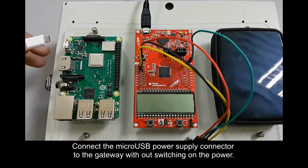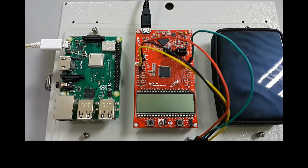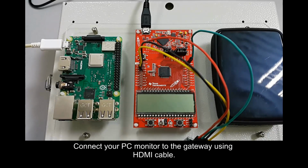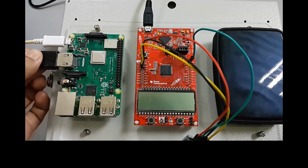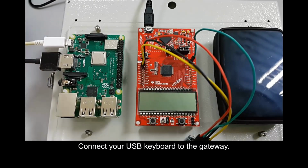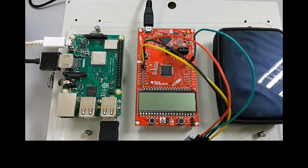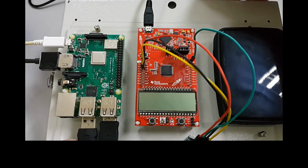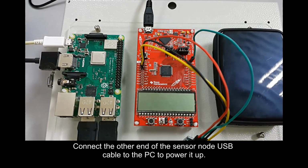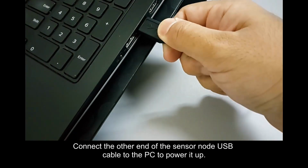Connect the micro USB power supply to the gateway without switching on the power. Connect your PC monitor to the gateway using the HDMI cable. Connect your USB keyboard to the gateway. Connect your USB mouse to the gateway. Connect the other end of the sensor node USB cable to the PC to power it up.